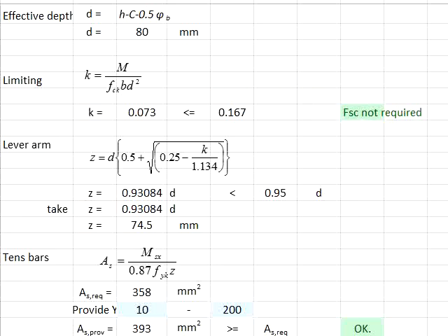You know that the design of the staircase is very similar to the slabs, where you have quite a large cross-sectional area as compared to the loads acting onto the member. It is not likely for you to have the compression reinforcement bar required, similar to the slabs. If you encounter a situation where you require the compression reinforcement bar, there is a likelihood that you might have some calculation steps wrongly computed. You should go back and check your calculation steps.